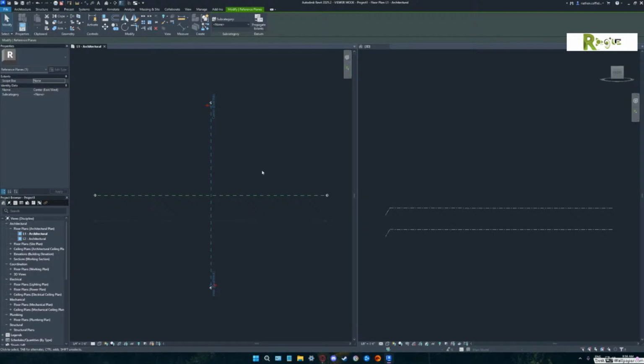Now, I want to show you a different way to select because this is going to be an important thing that you do. So, obviously, if you pick on an object and select, it turns blue and is selected. If I wanted to select, you notice how when you pick on that next one, it unselected the last one? Yeah. All right. Hold your control button down and pick another object. See how it's got both of them? Yeah. Now click once in what I would call white space and empty space.